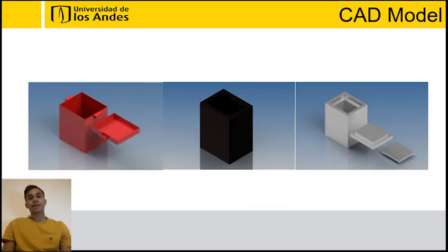The CAD model. The red component is the external coating, the black component is the shock absorbent system, and the last image presents the isolation piece, the closing seal, and cooling. In this model, the selection of materials was made additionally, adding the requirement of structural integrity using a vibration isolation foam, which fulfills both the function of absorbing vibrations and also being an extra layer that provides thermal resistance. And for improving isolation, a hermetic seal was added.